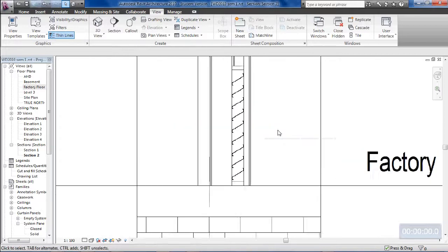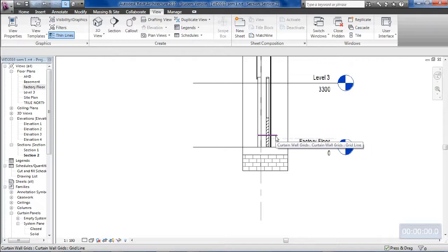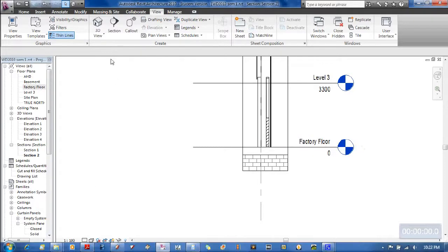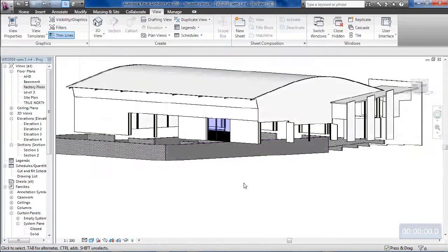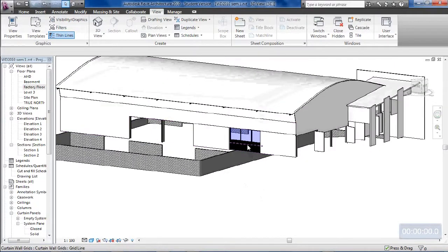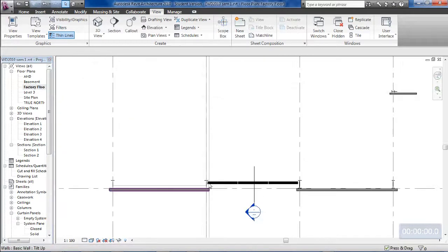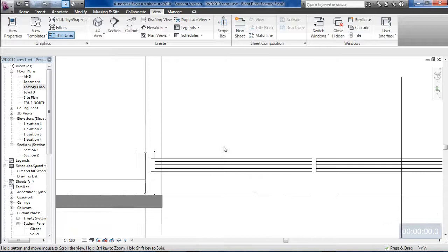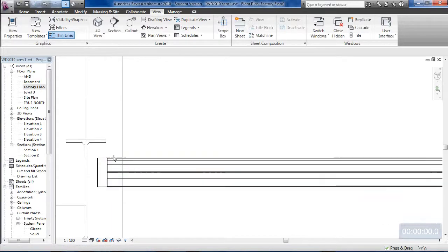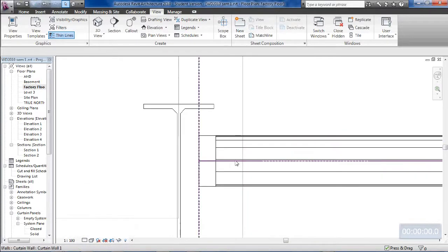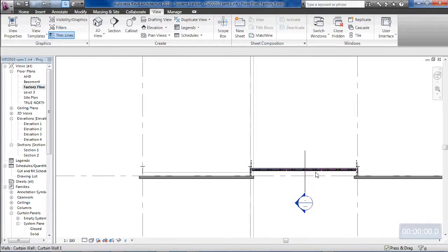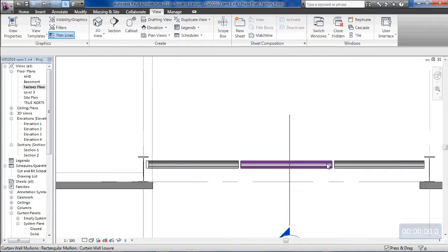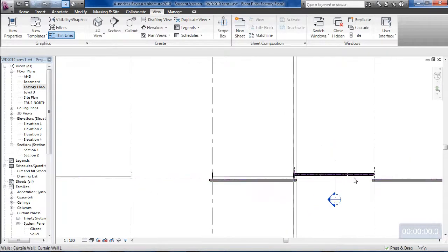Okay, so we've got those curtain walls done. So in the 3D view, we'll have a look at where we're up to at the moment. You've got some more curtain walls that you can place now. Oh, the other thing we should do with that curtain wall, just back at factory floor, is it's probably not in exactly the right position anymore. So what I want to do is I want to pick up the whole curtain wall. One thing I've noticed too is we're missing some of these mullions here, and I'll show you what happens with that, but I'll just get this into position correctly first.